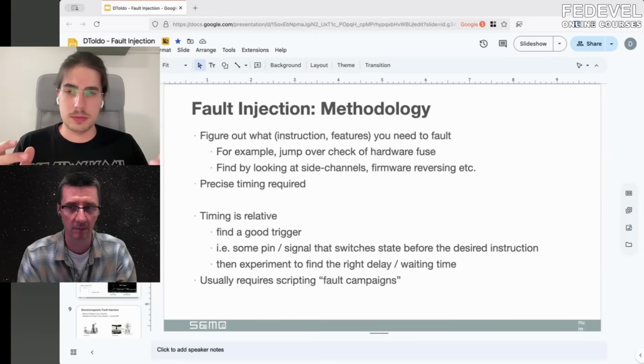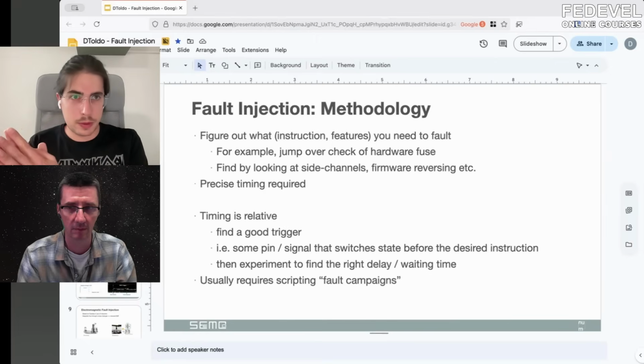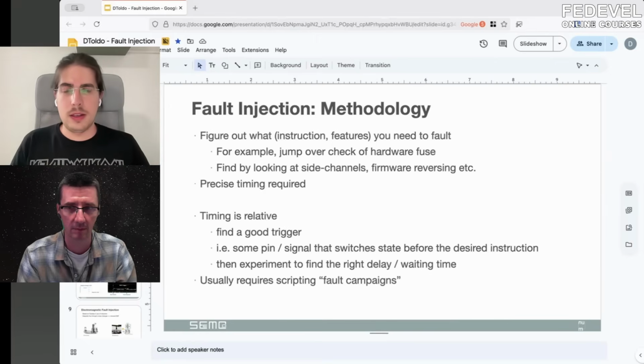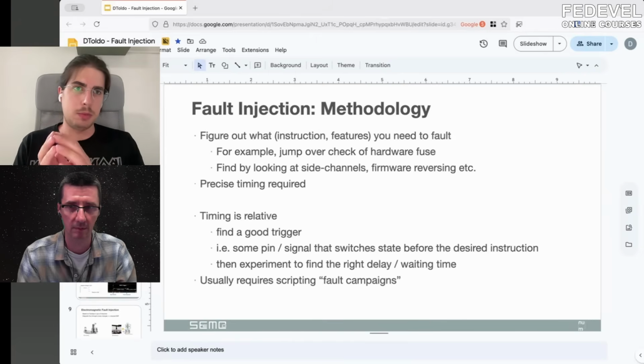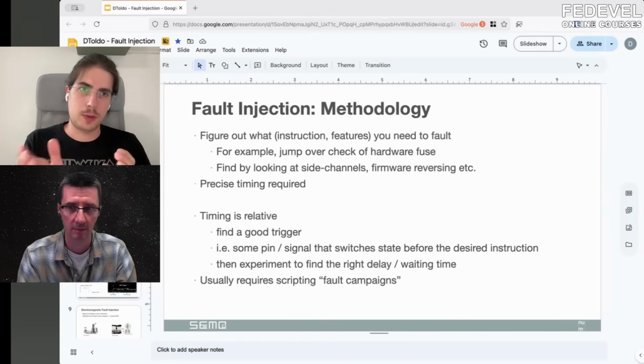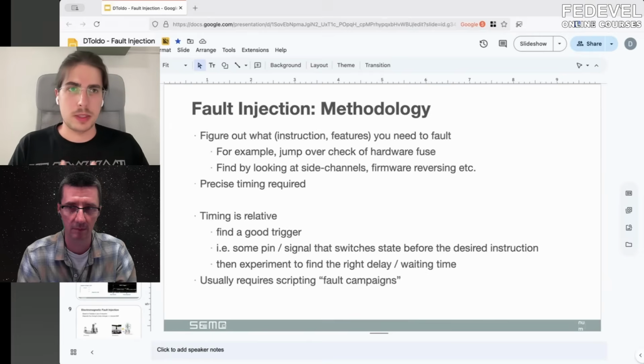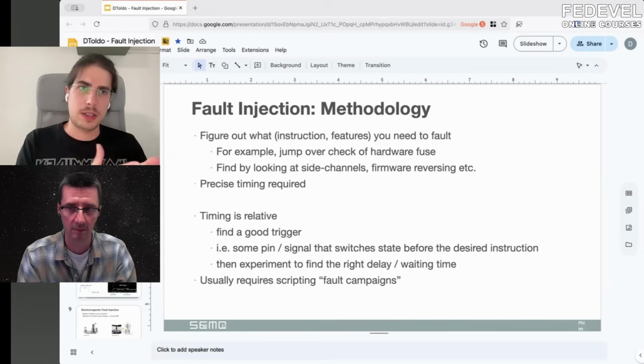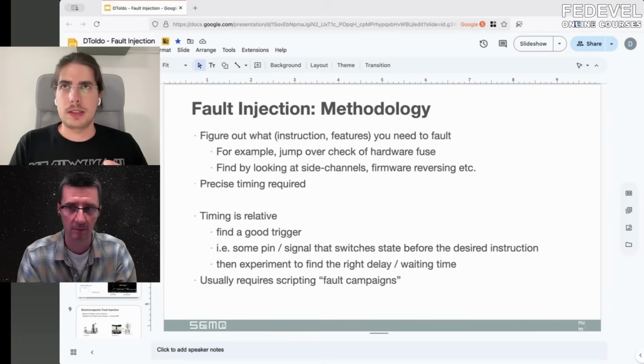Like if it's transferring encrypted firmware from one device to another. Let's say Apple AirTags: they have one chip that boots the second chip, basically it transfers the firmware after it boots, but it's encrypted. So we know that the second chip gets the firmware, decrypts it, and then runs it. This is something we know from prior analysis.